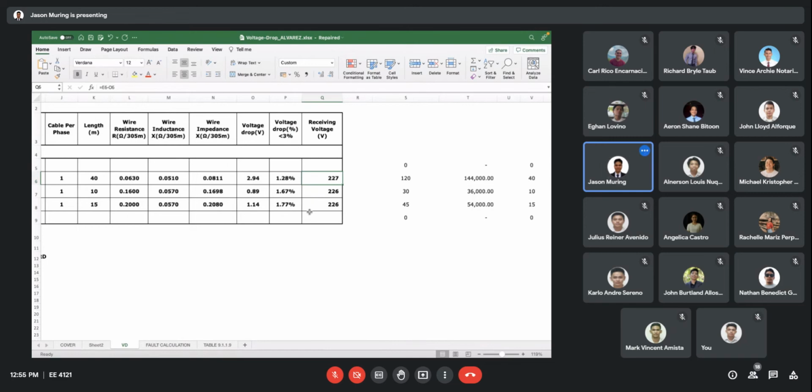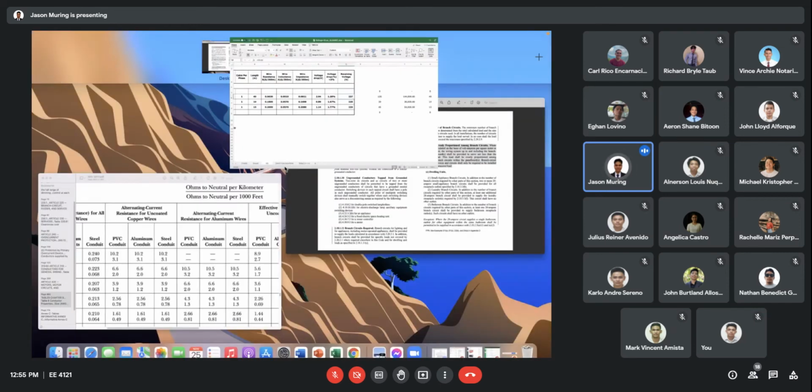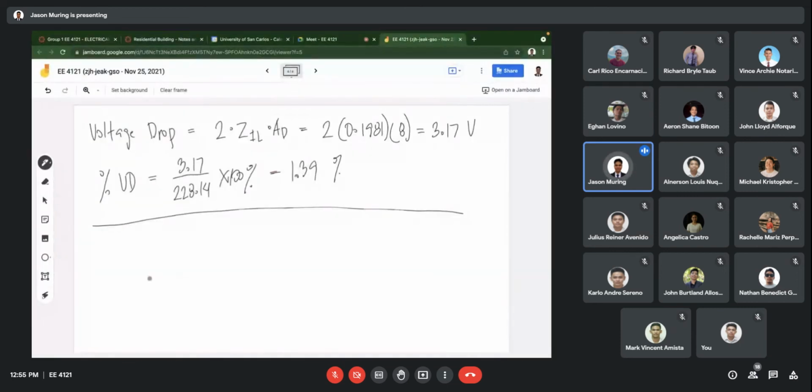Diba? So if you have 230, so 10%, so that's 23. So 23 volts fluctuation from 230, so meaning you can have a voltage from around 210 to 250. Okay, so if this is our nominal voltage, so this is 230, again, we can have variation of 10% plus minus. Okay, so meaning we can have here around 250 volts and here around 210 volts.